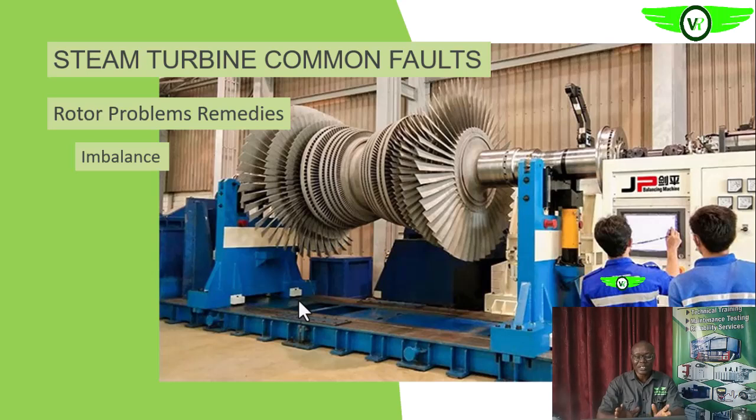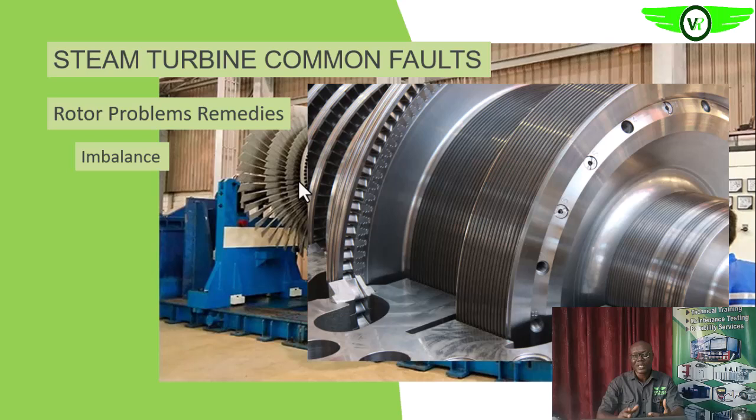So once it has been observed that we have that high one-times RPM and we confirm that we have unbalance, the only remedy is to balance the rotor. That is what we have here. We will see where the mass unbalance is, and then we either add weight or remove weight. All of these are meant to balance the rotor.